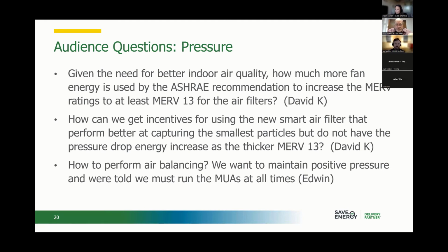Now, the second part of this question, how can we get incentives for using that? The incentive part of that, Jay, I'll defer that one to you because I'm not quite sure. From a mechanical perspective, all this revolves around doing some testing and understanding what's going on with your system. I keep getting back to this low duty cycle, because as soon as the filter starts getting dirty, the fan operating point is changing, because now for the same amount of flow, you have to have the fan cranked up more to build the pressure to overcome the extra loss.